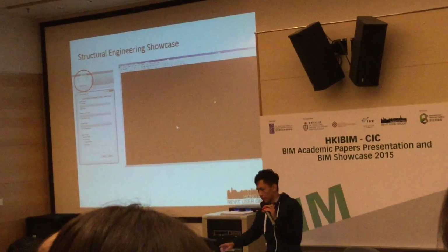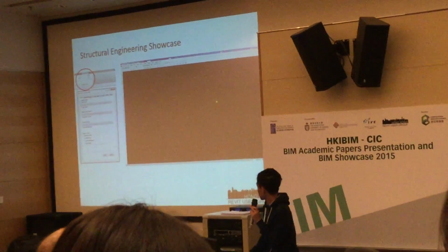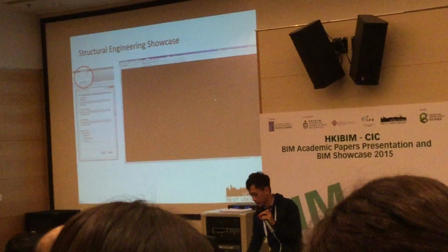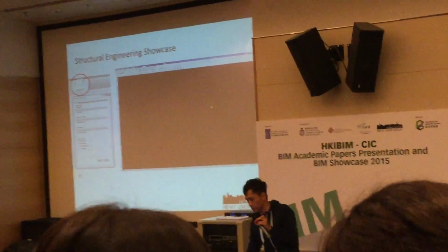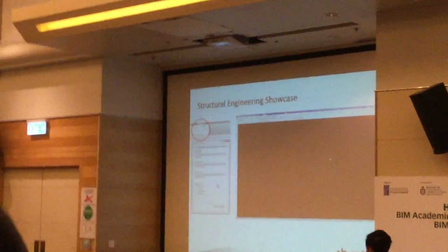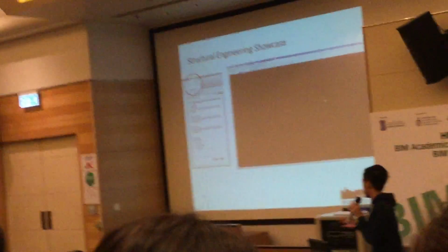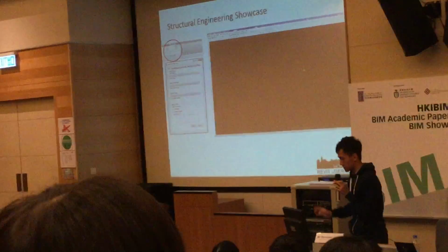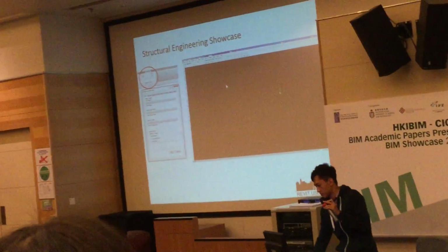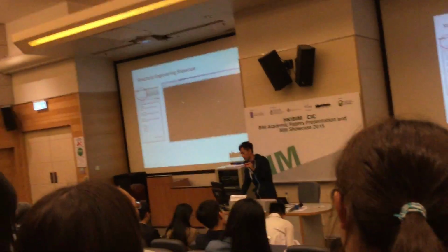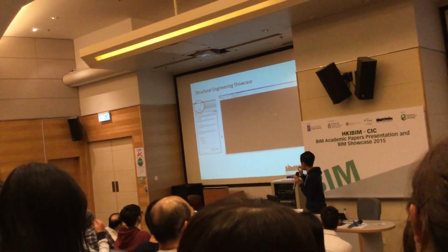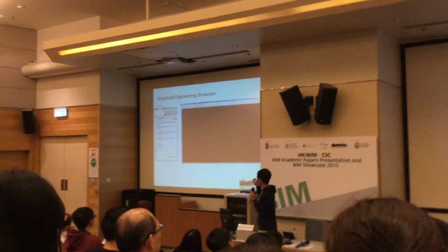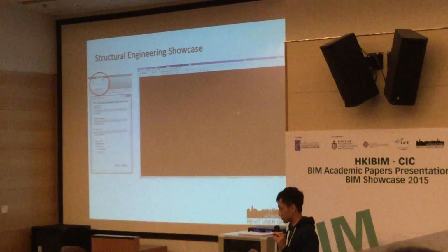So here I use an add-in plugin called export to ETABS, and it's very simple. You basically export the things you want to ETABS, which is not what I use at my place. And you can see the geometries are basically the same, but then you don't have the loading, you have the geometry, and only the geometry. You have to further fine tune it for your analysis.